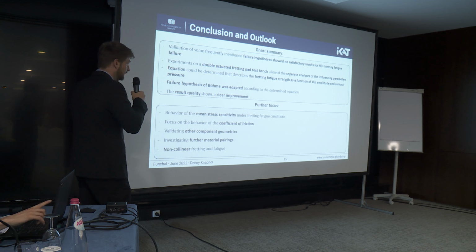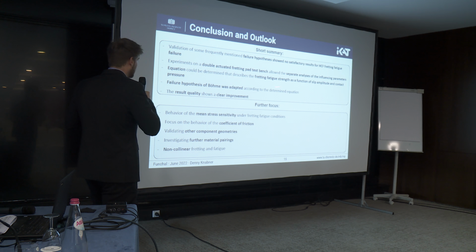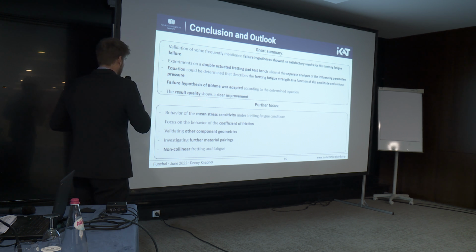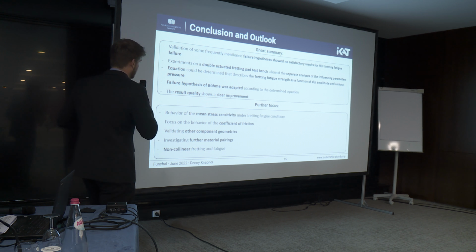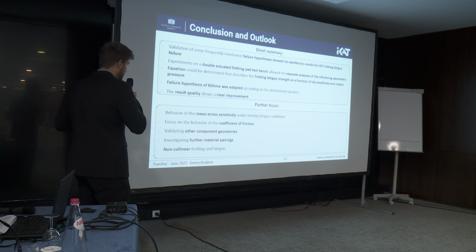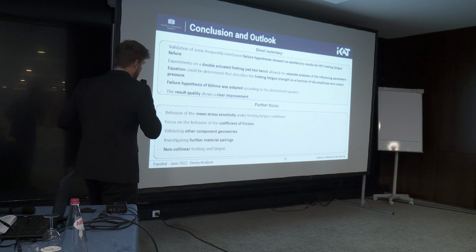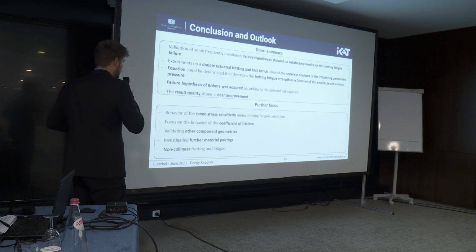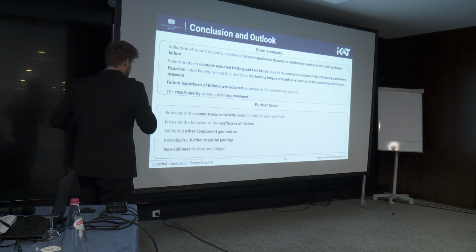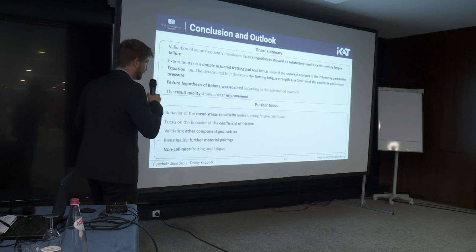To get better than what we have, in the future we will focus on the behavior of the mean stress sensitivity and the behavior of the coefficient of friction under these fretting fatigue conditions. Also, we have to validate other component geometries and investigate further material pairings, and also non-collinear fretting and fatigue is something we have to focus on.